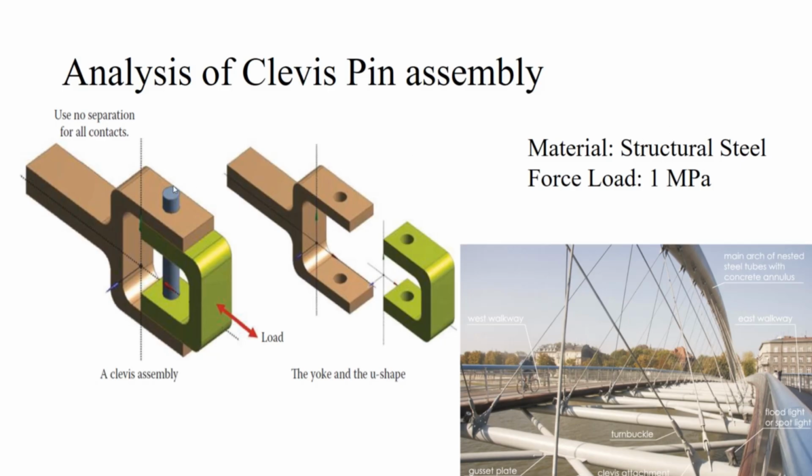What we are going to do is create the contacts, and we are going to use the no separation contact behavior for all the contacts. Then we are going to study the stresses that occur in each individual part, and also we are going to see how to use the contact tool present inside ANSYS Mechanical. Thank you.